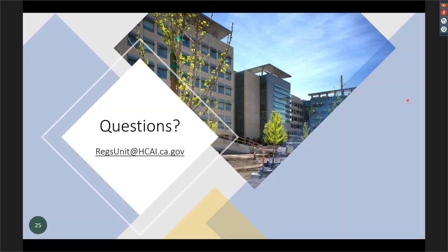Any ASI, RFI, NMA will all be documented on the plans because you're modifying what's on the approved plans. Your delta and your cloud just designate how it was modified and what tool was used to modify it. So yes, every NMA should be on there, just as every RFI that requires an annotation or ASI would be.